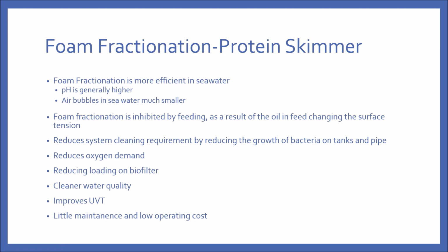Essentially, by removing excess protein and fine molecules, the bacteria will not have so much excess feed to feed on, reducing their growth. And since we know that biofiltration is an oxygen demand process, by reducing the loading on the biofiltration, we can also increase the oxygen availability in a RAS system. It also ensures a cleaner water quality and improves UV transmission.